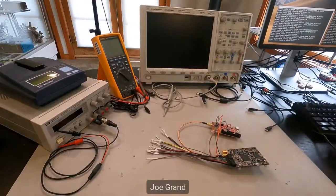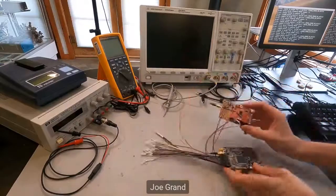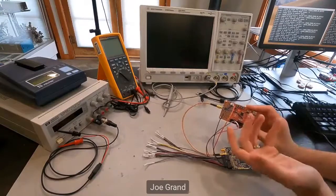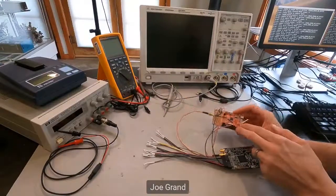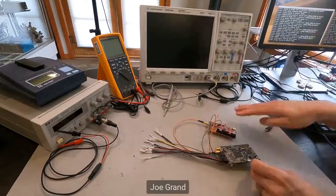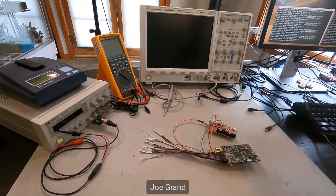Okay, so I have this device. This is more advanced. This is called voltage glitching. What we're doing is basically this microcontroller has some code in it. There's code protection to prevent us from reading the contents out. So if we did put it in a device programmer, that wouldn't work. So we're basically tricking the system and causing it to corrupt a read during the boot process to skip over the check, or to invalidate the check of saying, hey, is this chip supposed to be protected or not?